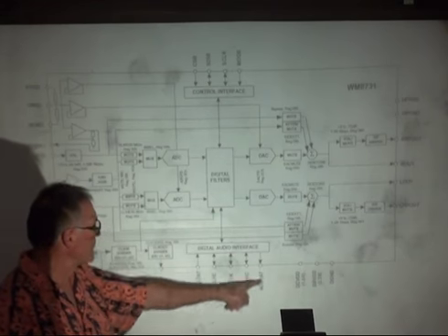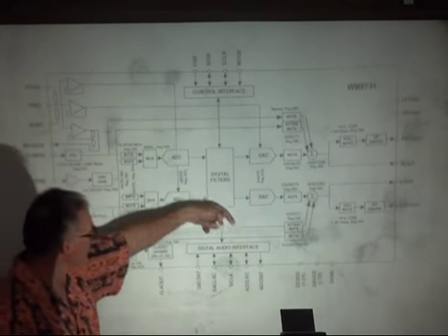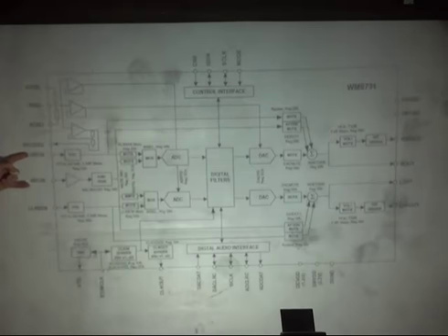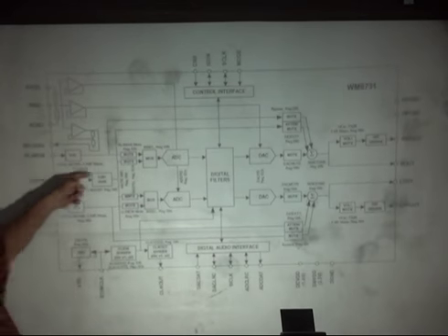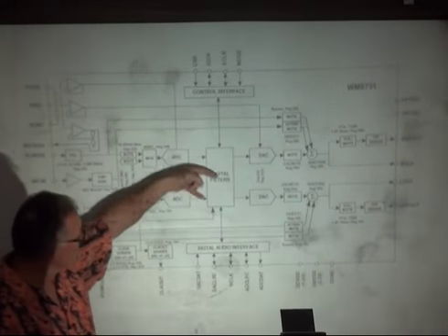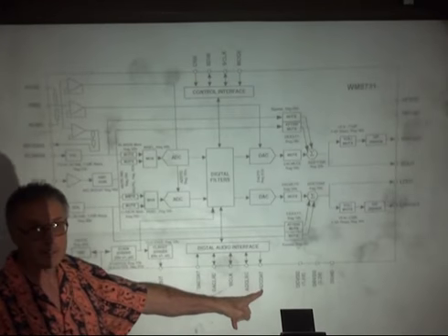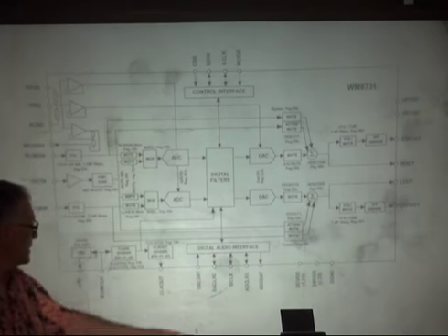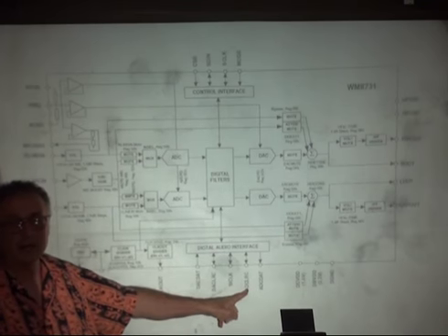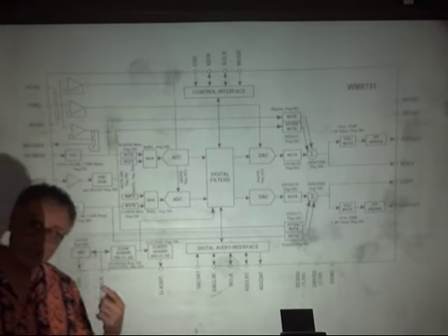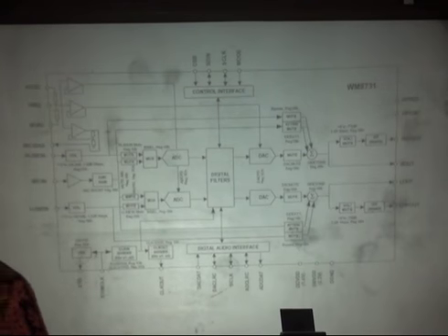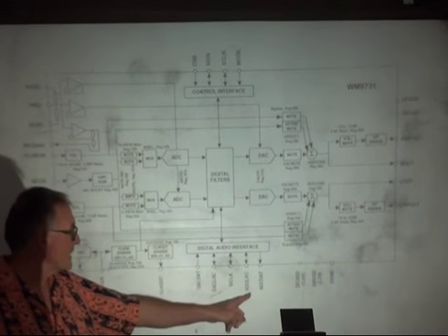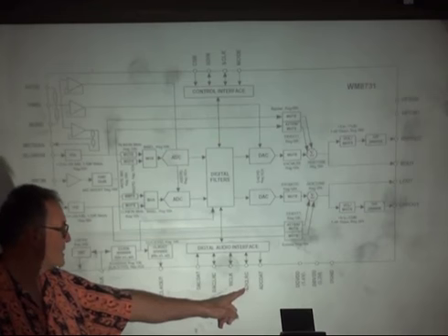ADC data comes from the analog to digital converter. So your line in, your mic in, all come through the ADC converters and end up at ADC data. So you can read those from the FPGA. There's an ADC left-right clock, which synchronizes the left and right channel with what's being read or written to the Wolfson chip. That, in this case, is going to be generated by the FPGA.